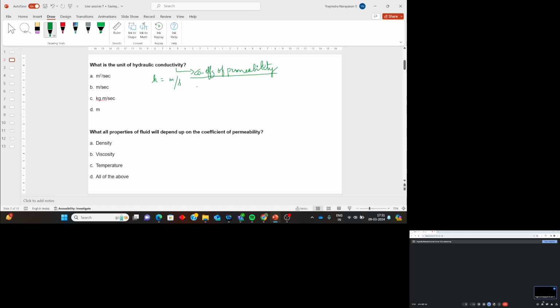If we use the term bluntly as permeability, it is completely different from coefficient of permeability. The term permeability is denoted by capital K, which is the porous media property, which depends on the pore structure, grain size, etc. of the soil mass through which the flow is occurring.